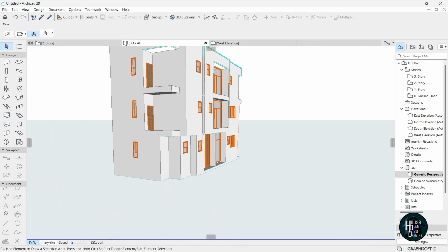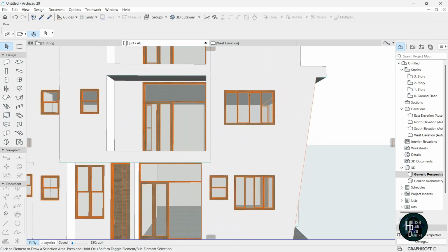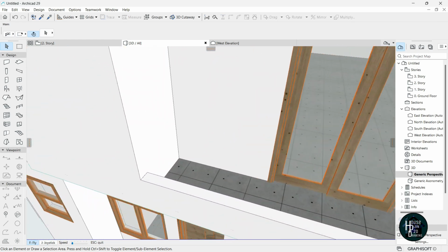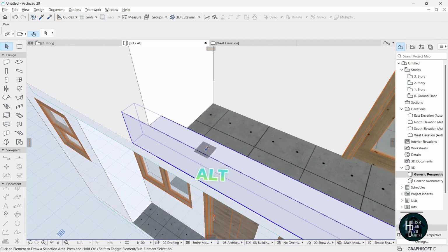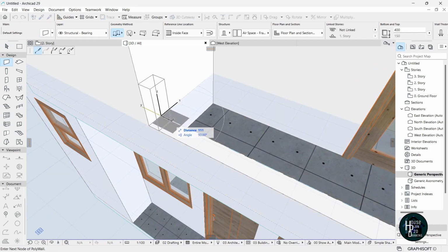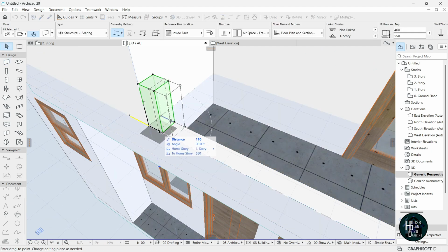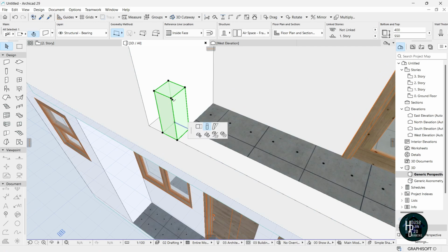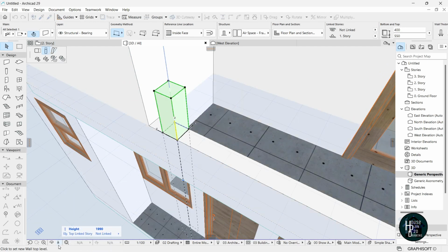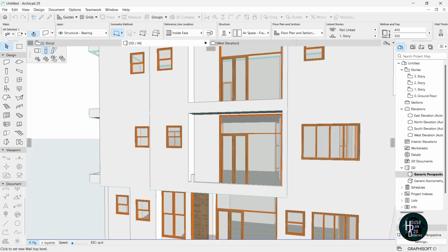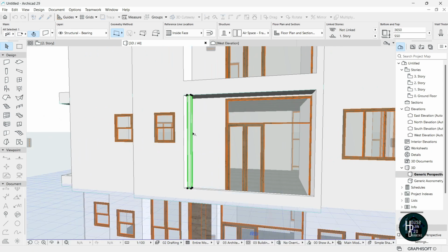The next thing we're going to do is add the wall design. What I mean by the wall design is this. Hold on alt, select this, just click and give a distance of maybe say 150. Click enter twice. So click this, press Ctrl+D, click this point, put it here. Okay, click on this node and we're going to stretch this upwards and then select that story right there.